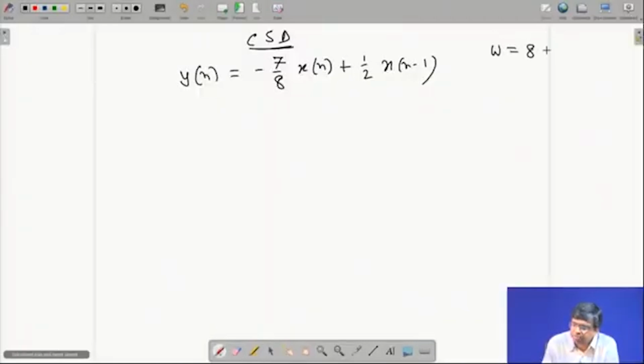Suppose we are told what size, this is important, is 8 bit. That means x(n) as well as y(n) are all 8-bit buses when the bits are coming in parallel. So there are 8 bit lines and that forms a bus. But we are now considering bit serial operation, right? Bit serial. That means there will be only one line through which the bits, LSB, next to LSB, and so on up to MSB, will come one after another for one word. Which means in terms of timing diagram, there will be only one line. You will have got one bit, next bit, and so on.